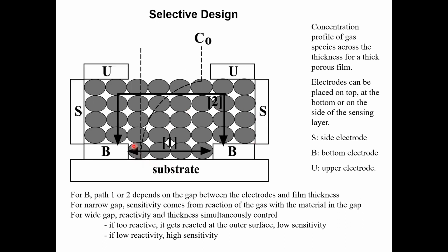So for example, if the gap is small and the thickness is large, what will happen is that your highly reactive gas will quickly react at the top surface and the signal will never reach the electrode to pick up the response.